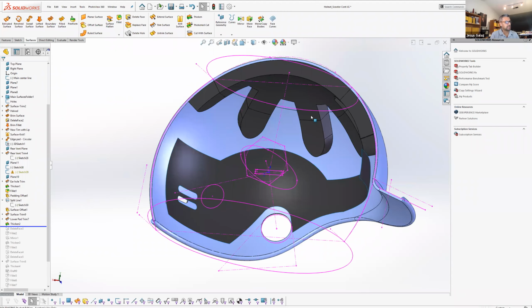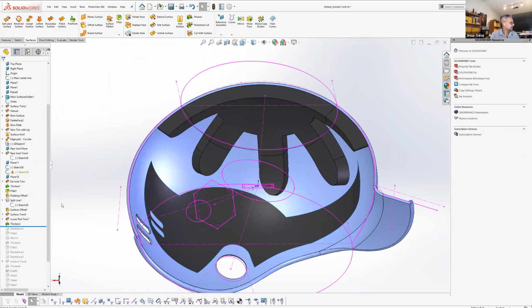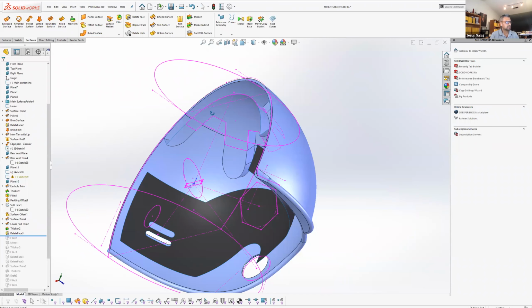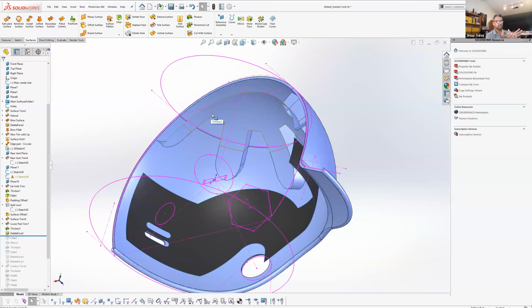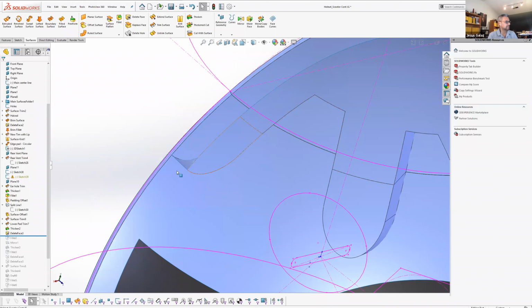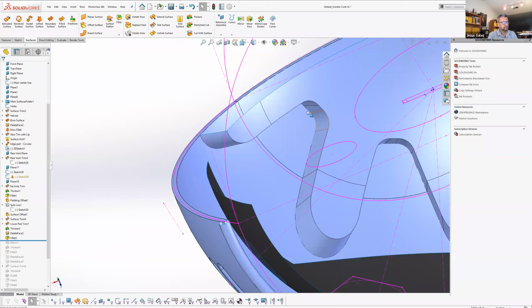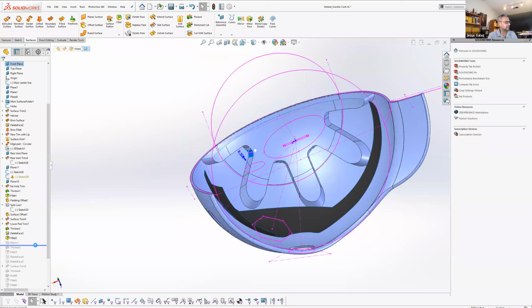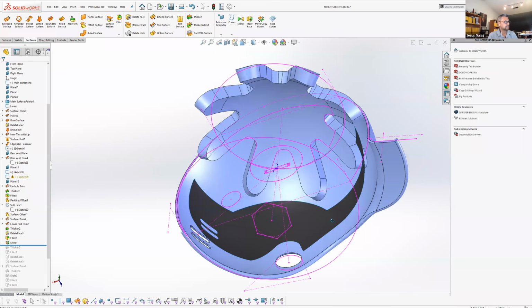And then I thickened the top part. I was having trouble, you may run across this, mirroring this and having them come together because of a zero sum surface. So sometimes you may get that problem. In this case, what I did was I deleted the middle face of these. I added some fillets to the interior corners to smooth those out. And then I mirrored it. So that's the top piece there.